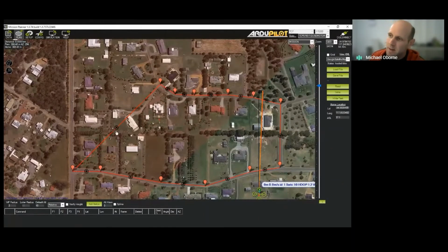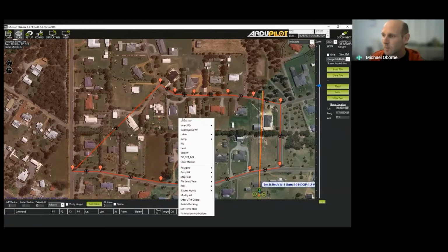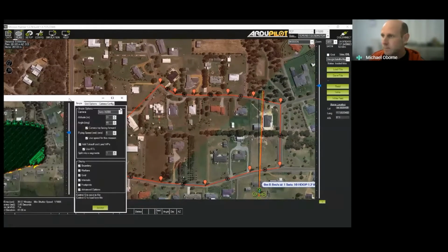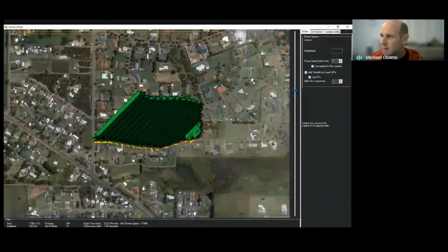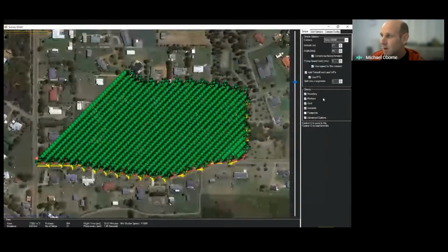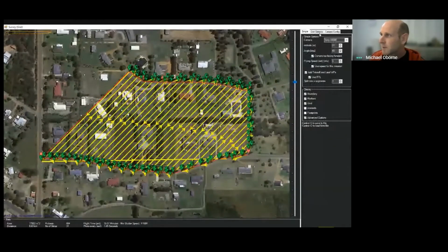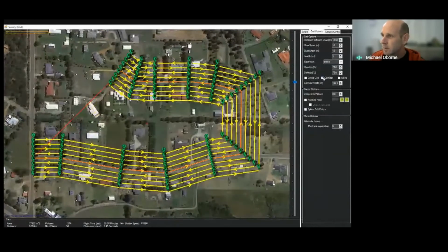There's currently a bug in Mission Planner where it draws this extra line here. That's because obviously I don't know that you're going to be drawing a corridor just yet, where I still think you may be going a polygon or a survey grid. So what we'll do is we'll just go straight to survey grid. So currently that's opened here. There is a lot of points. So I'm going to turn that into a corridor.